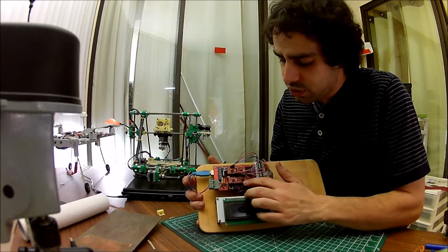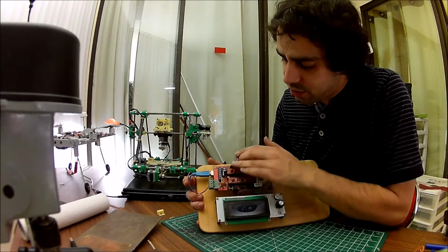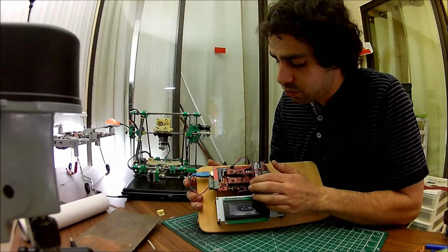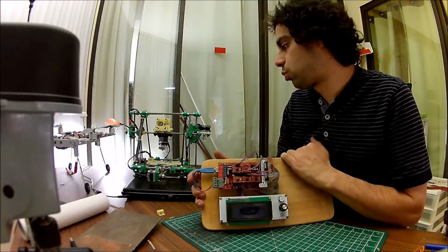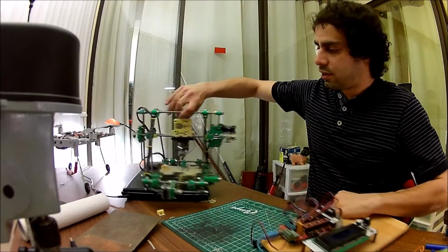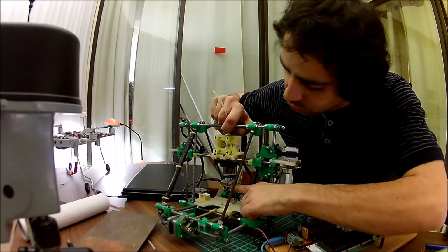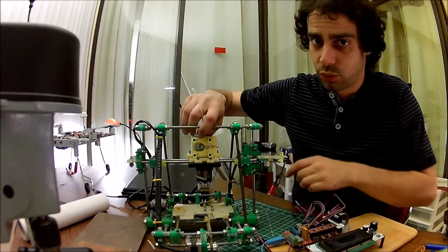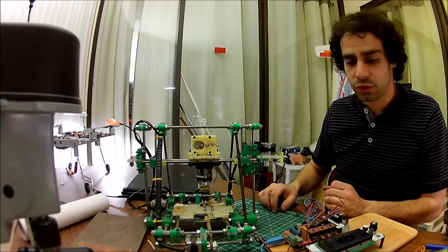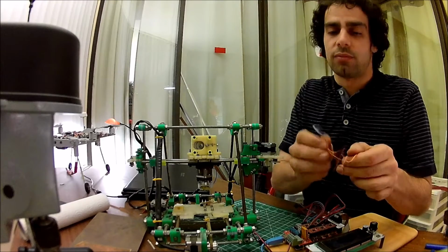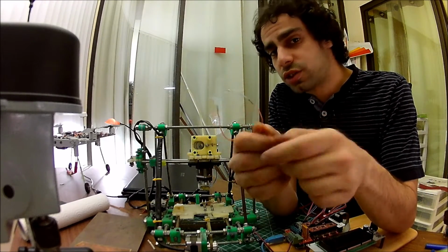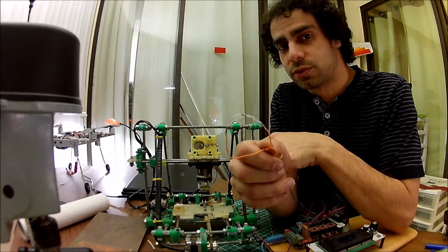Now, you may have noticed in these motor drivers that there seems to be one extra motor driver. Well, that's because one of these drivers is actually being used to control the hot end. Inside the hot end, we have a resistor, a large resistor that heats up this block, which melts our thermoplastic. The temperature control is modulated using a thermistor or a thermocouple. This is actually the particular thermistor required for this machine.